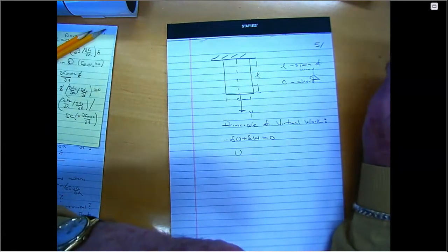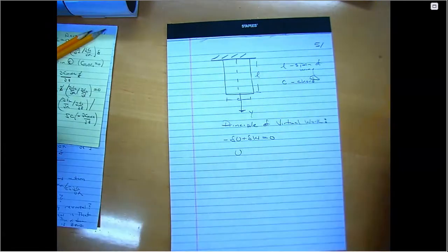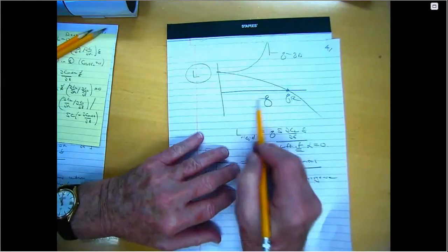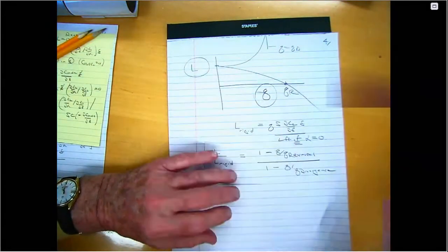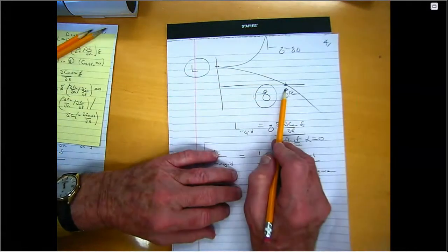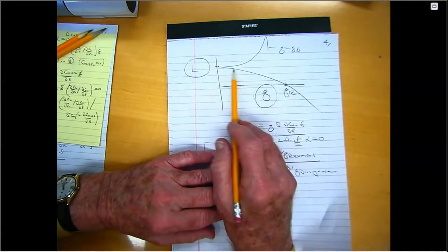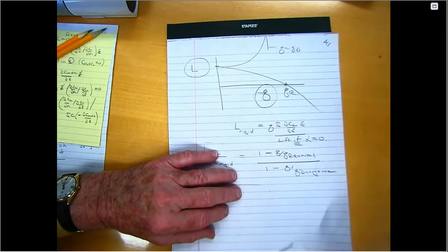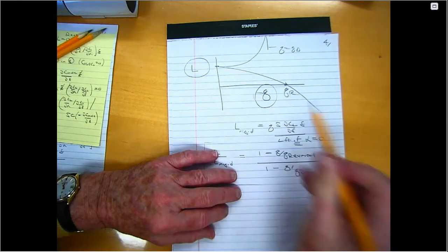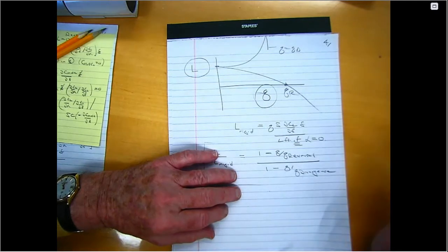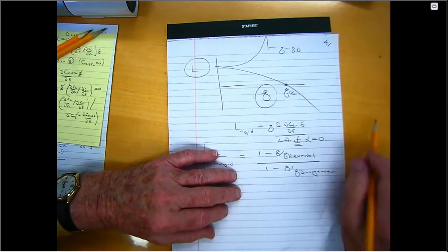But in general, if I plot lift versus dynamic pressure, the lift isn't 0. But there is a Q where it is 0. Below that, the lift is positive, meaning that if I rotate the control surface down, the lift is up. Whereas if I'm greater than the reversal condition, if I rotate the control surface down, the lift is actually down.